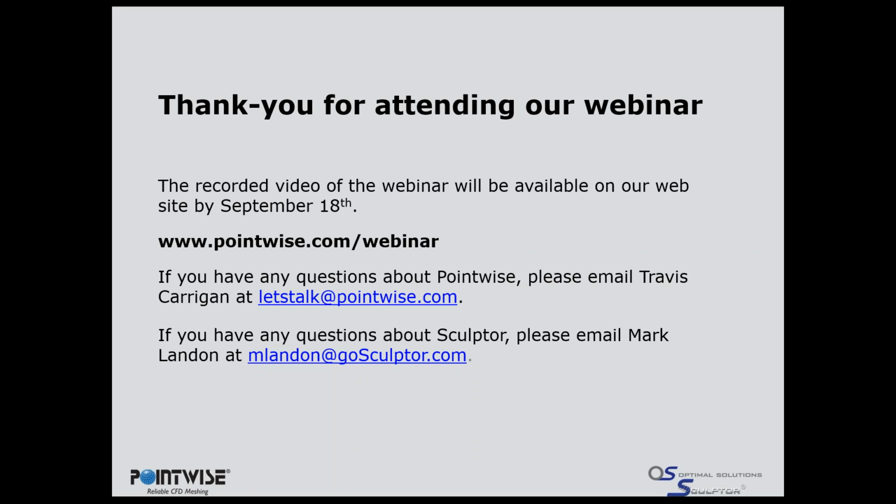Right, and the actual deformation itself and the effect on the nodes in the mesh is rather isolated, is it not? Yes, it's local. You have local control. So if we're moving a control point near the rear of the car, up to 2 control points away from it in any direction is not moved at all.